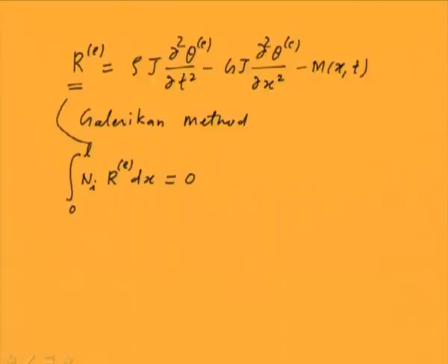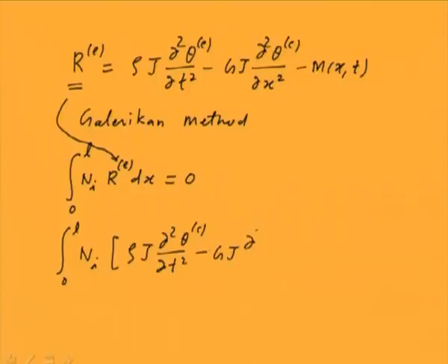So we will be substituting this here. I am showing these steps so that the concepts are more clear. Okay. Here you can see that especially the derivative with respect to x of theta, that angular displacement, is second order. So, we would like to reduce this, because by reducing this we can choose a lesser degree polynomial as our solution. So, now we will be reducing this differentiation by integration by parts.